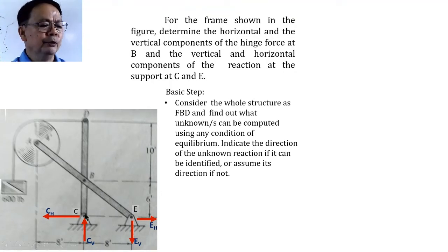Ganon din, if we will take moment about C, all the 3, C sub H, C sub B, at itong horizontal component ng E, will also create the moment about C. And therefore, we shall be getting a moment equation that involves E sub B, and E sub B therefore can be computed. Di ba ga?